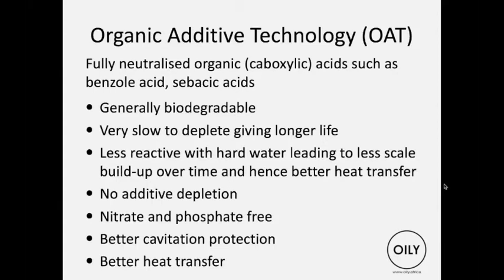The OATs: fully neutralized organic carboxylic acid, generally biodegradable, very slow to deplete, giving longer life, less reactive with hard water, leading to less scale buildup in the engine, better heat transfer, no additive depletion, nitrate, phosphate-free, better cavitation protection for your heavy-duty diesels, and better heat transfer. So OATs are the Rolls-Royce.